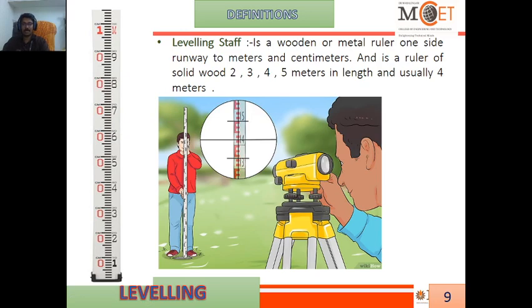I have explained this least count in one previous video, right? I hope you will remember. From the bottom, the gradings are there, each alternate white, black, white, black, white, black. Higher up, it is given 0, 1, that is 0.1 meter, 0.2 meter, 0.3, 4, 5, 6, like that, up to this is 1 meter.